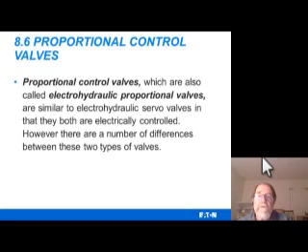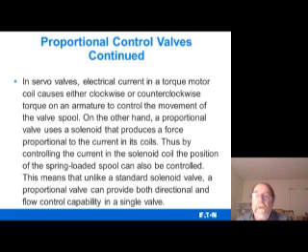Proportional control valves, which are also called electrohydraulic proportional valves, are similar to electrohydraulic servo valves in that they both are electrically controlled. However, there are a number of differences between these two valves. In servo valves, electrical current in a torque motor coil causes either clockwise or counterclockwise torque on an armature to control the movement of the valve spool.